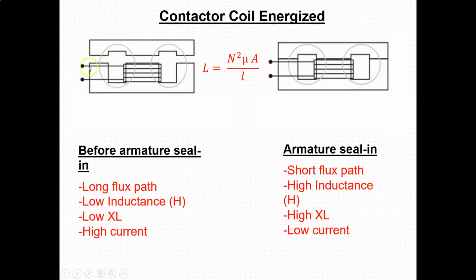If I put anything above 120 volts, say 130 volts, it might be okay. If I get much higher than that, I'm running a risk because my voltage is going up. It means my current's going up, and I'm going to burn out my coil.